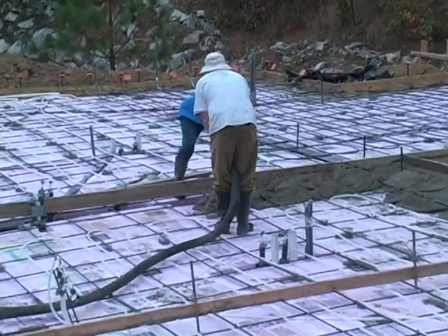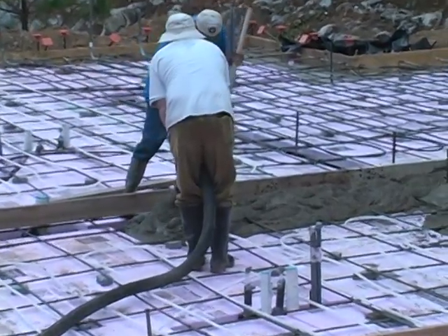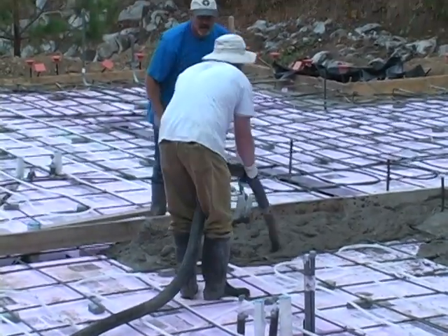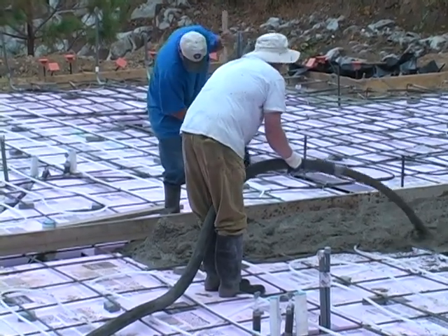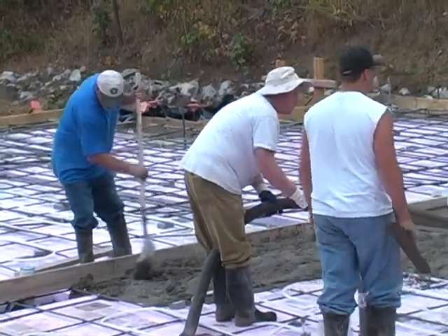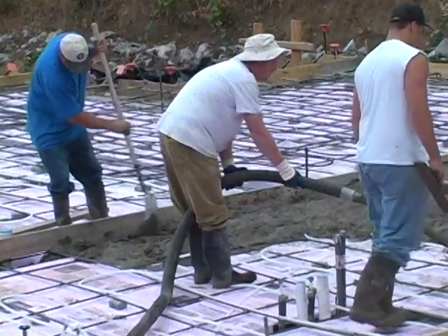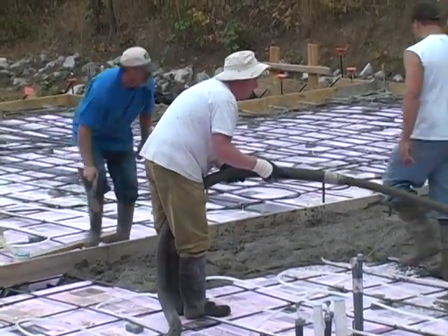We don't want to try to cover too much at once, because with weather conditions and so forth, it'll be hard to finish the concrete in a way that will actually do a good quality finish. So we pour just enough that we can handle in a day. You want to make sure to get it all in place underneath our removable screed boards here, so we don't have any gaps. Again, just continuing to pump all the way across.